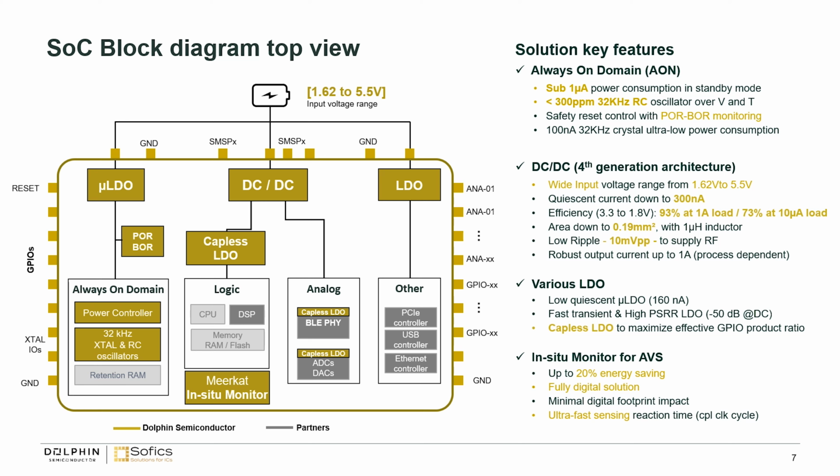Therefore, what you want to do when you design such a product is to make sure that you have a maximum of efficient pins like GPIOs. I give you an example. If you design a wireless product on a 28 pin package, you will have some pins dedicated for the RF and so on, maybe 10, maybe 15. Therefore, on a 28 pin package, you have only 13 pins available, right? What if you can get more?